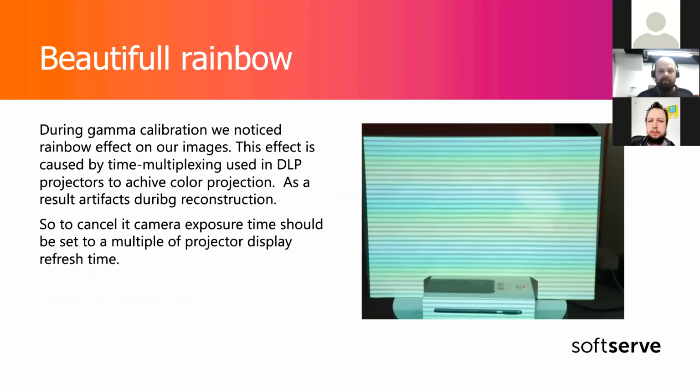Basically, how it works: the projector has a circular filter with 4 sectors. 3 of them are RGB, and the last one is just blank. And the DLP projector, using mirrors, constructs the images from the individual colors on the plane. So it's actually tricking our eyes, of course, and projecting RGB frames one by one.